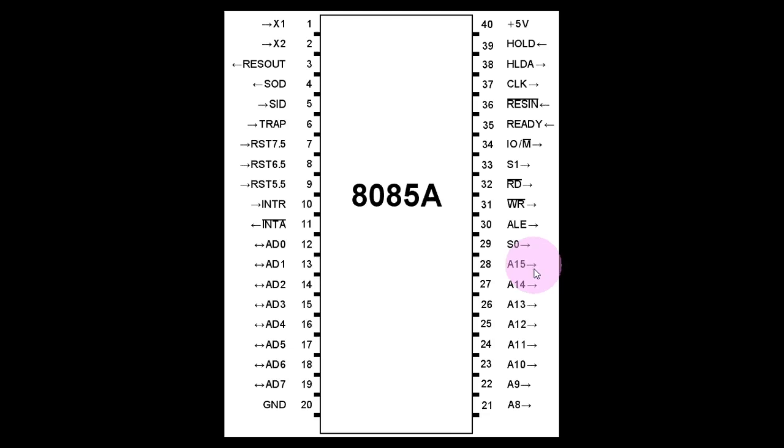Then you would like the externally interfaced memory to transfer some data to the microprocessor, and that will be done through AD0 to AD7, because every location in memory is also of 8 bits. So this is the logical sequence. In the beginning of the operation, you transfer only address, and once the address has been transferred, you will mostly be transferring data to or from the memory.